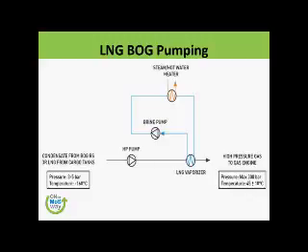So the good thing about all these LNG ships is that they run on LNG fuel. Mind that some of the Q-Flex, Q-Max models are not consuming LNG for their boil off; they are just using gas oil and diesel oil.